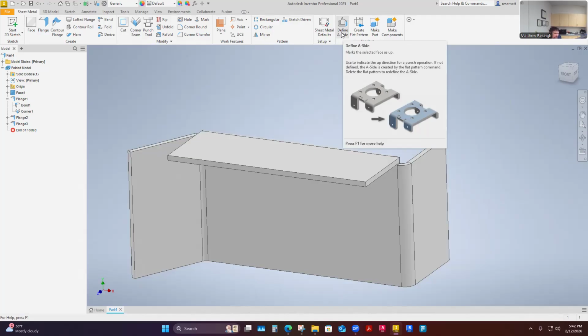So if I choose an A side, I'm knowing the part's intent. Generally machines, if you've established an A side, will recognize the A side is up in the machine, meaning it's not the side that's been laid down against the laser table or the plasma table that's holding the sheet while the laser is cutting it. Even if we load materials into our Glowforge laser, one side of that material is resting against a rough surface where things have been cut and sharp.